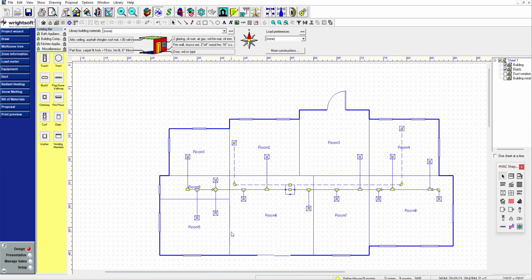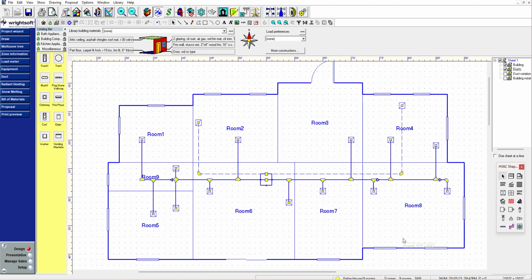Manual J said, they specify in section, I believe it's A8-8, that after the air, okay, so there's air flowing through these ducts. And every time it branches off to some other supply duct, the air starts to slow down a little bit.